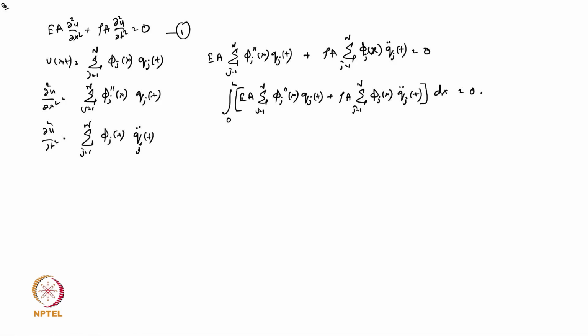If I integrate it over the domain, first of all, am I able to do that integration over the domain? I'm saying that the differential equation is 0. Now, next step, I am just doing the integration on top of it. First of all, can I do that? If you think about it practically, what is happening? You are saying that each element is satisfying the equilibrium, so obviously the whole domain is also satisfying the equilibrium. That's why you are eligible to do that integration over the domain.